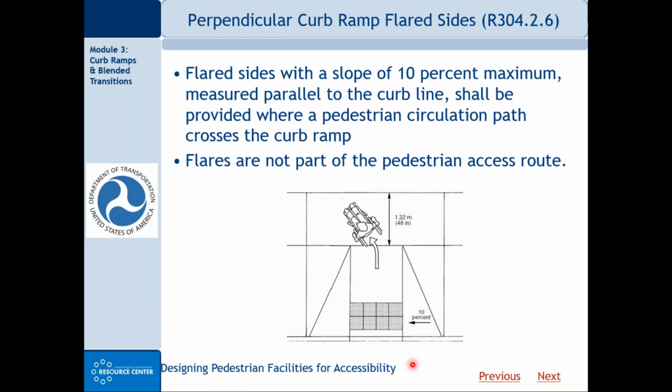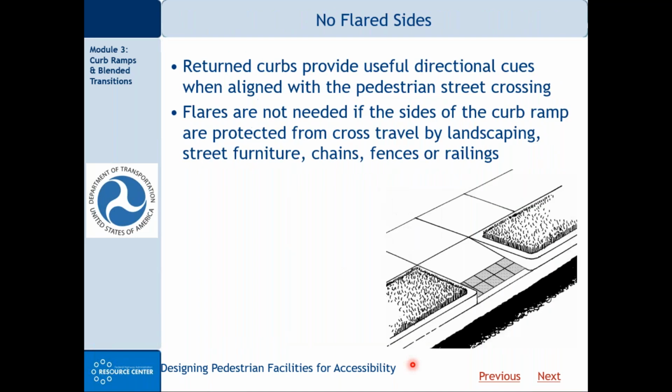That's a great question, and again, I hate to kind of evade these questions, but I think the answer is going to be it depends. In resurfacing, if you could do it, I think it would be better to correct that and make it 5%, the running slope for crossing the street. But I appreciate that given drainage and other things, you may not be able to do that. So in that case, it would be best to document that with a technical infeasibility. Good question. Thank you, Ron.